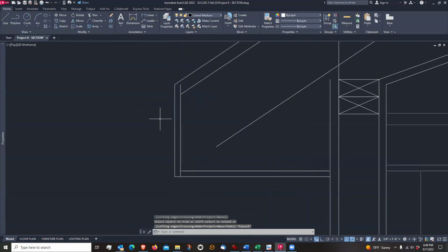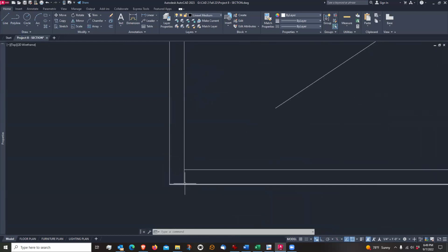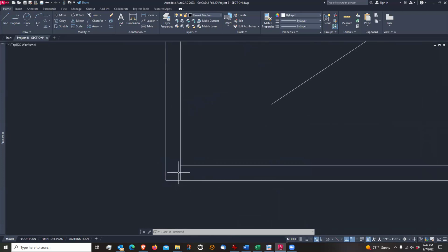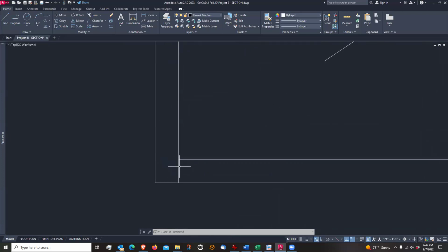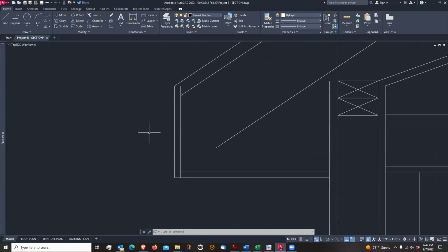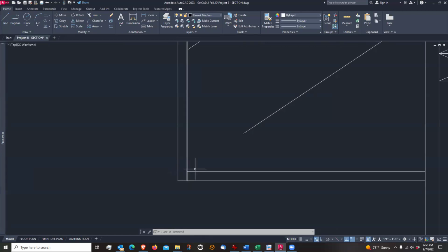So when we're drawing this, we want the joint. This is sort of a joint between a piece of finished wood here, and a piece of wood here, or maybe it's aluminum siding or something like that. But the joint between the two is right here. It's a vertical joint, not a horizontal joint. And the reason is, if it's a horizontal joint and it's raining, water can seep into that horizontal joint. Whereas if it's down here and it's raining, the underside of this could get wet, but then it would have to travel up here to get up into here. It's a lot harder for it to do.